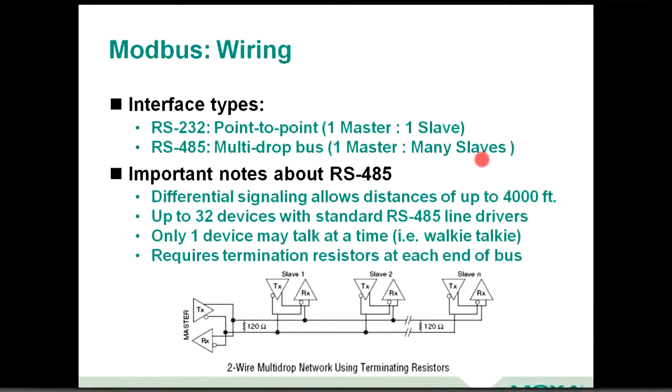And you can see a little bit here for those of you that maybe have a little engineering background or maintenance electrical background. You can see the master over here on the left having both the transmitter and receiver sharing a common pair of wires amongst these devices, and then each slave being able to receive and transmit by controlling its access to the network. Now understand this works a little bit like a shared media. And much like if you've done any RF work, it has a requirement that you have to terminate the ends of your network.